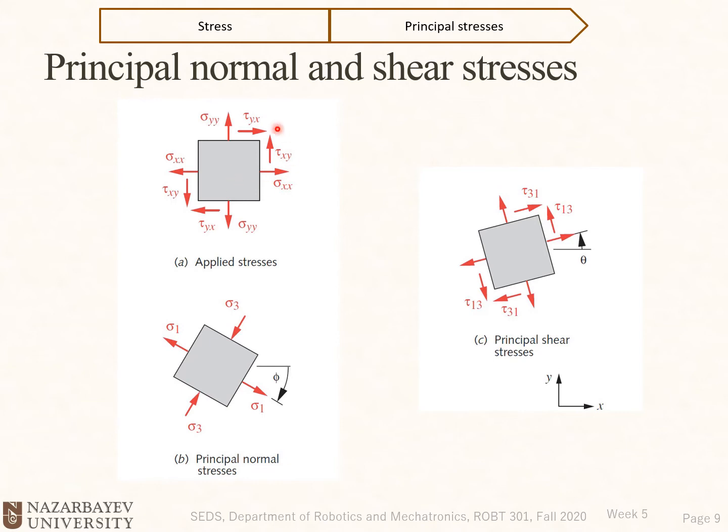The coordinate system we chose for this cube is based on the forces and the stresses applied to the part, and it's easier for us to analyze our stresses based on this coordinate system. That's why we chose this specific coordinate system. Again, this cube represents one point of the part.